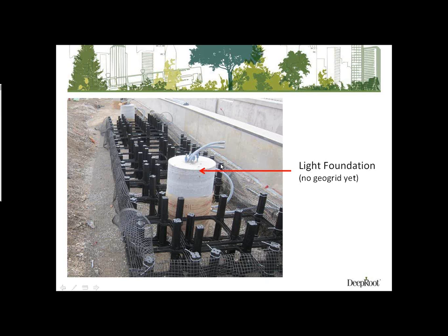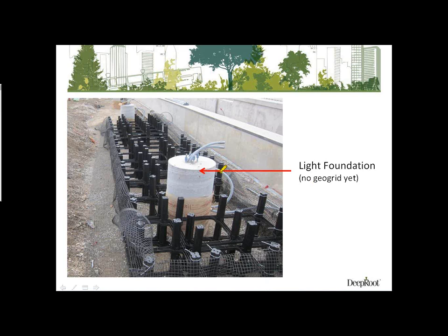Here's a light basin on one of the waterfront Toronto projects. Again, the GeoGrid hasn't been installed all the way around. You can see it on the back side and on the front side, but you don't necessarily see it around here. It should be going around the back side, around this side, and around here to completely enclose it.